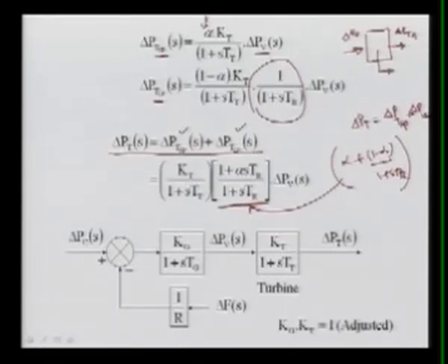So we will have a simple turbine transfer function that is written here, and I have used the simple turbine without reheating facility. So it will come here, this turbine model. This is the governor model, if you remember, which I derived in lecture number 1. Now this PV which is coming, here what is happening: this change in PC is a change in the reference setting. Here change in the frequency is coming through the drooping characteristic with the negative sign.